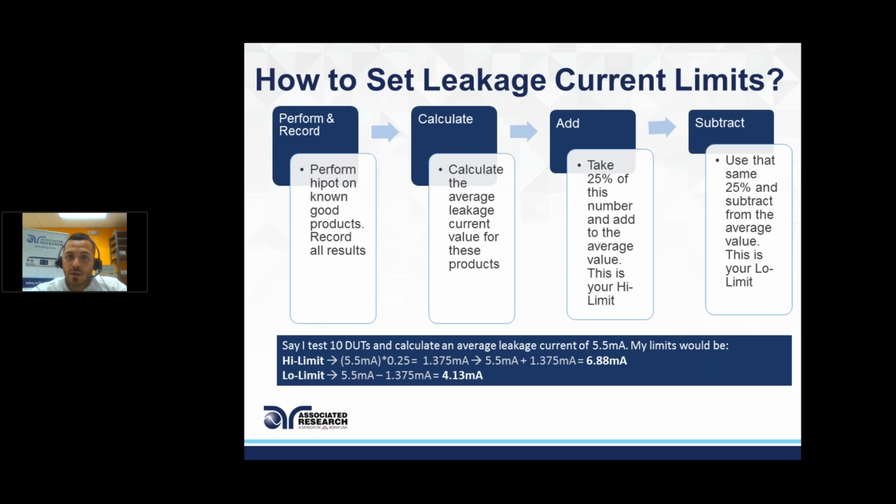If you're not sure, if you haven't got that info from your standard yet, or your NRTL, nationally recognized testing lab auditor or engineer, take 2 times your rated voltage plus 1,000. Great, now I know what my test voltage is. What are my limits? Now we'll discuss how to set your limits.